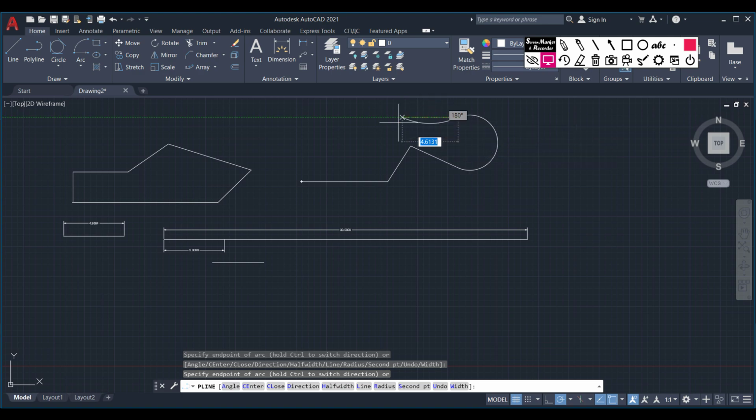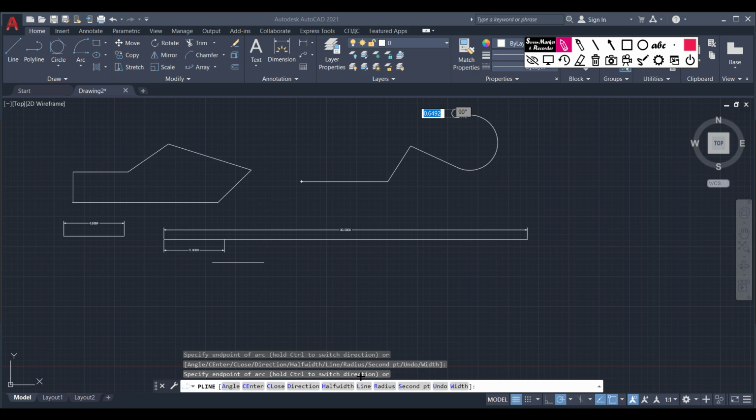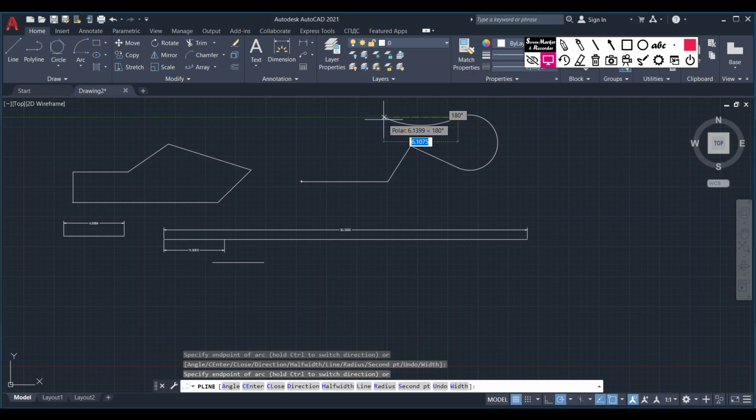What if we again wanted to draw with our line tool from here? If we go back in here, you can see there is another command for line. So if you press L from here, I'm pressing L from my keyboard. Now space. So I have enabled the line tool again.